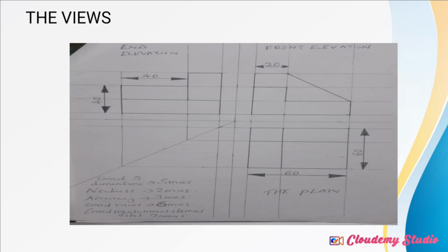So I always say that when drawing, you have to draw vertical and horizontal lines. You are drawing the x and y axis, and then you have to be spaced 10 millimeters from the main axis to get the axis where you'll be required to draw the drawings.